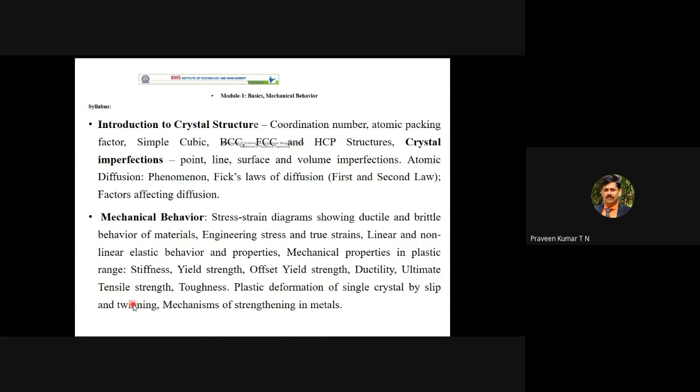One side you are saying plastic deformation. First, why I am telling this repeatedly, I am using some words, so first you have to understand what plastic deformation is. Imagine you have a steel rod used in the construction industry. There is a group of people referred to as bar benders. It is one profession itself. They bend the steel rod depending upon their requirement, with some hooks. They will pull and bend, and it is permanently set. That is plastic deformation or permanent deformation. The correct term used is plastic deformation.